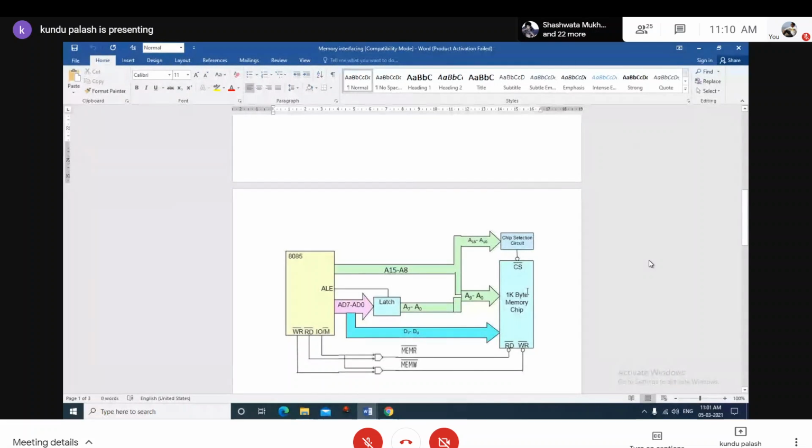But the memory chips are available with the address signals, which are the input signals to the memory chips, the data bus signals, which are bidirectional, that is, input as well as output during the reading of the information from the address location. And the minimum control signals needed to enable the memory chip are a chip enable or chip select signal, which is normally active low, as well as two other control input signals coming from the microprocessor, the read bar and the write bar. These are the three important timing signals under whose action the memory can be accessed by any CPU, that is 8085.